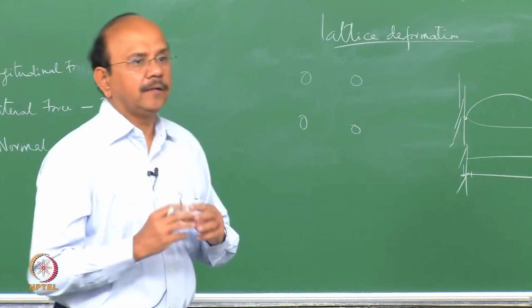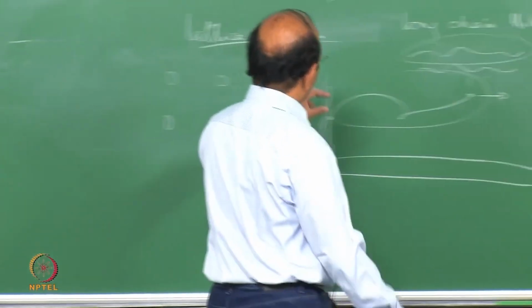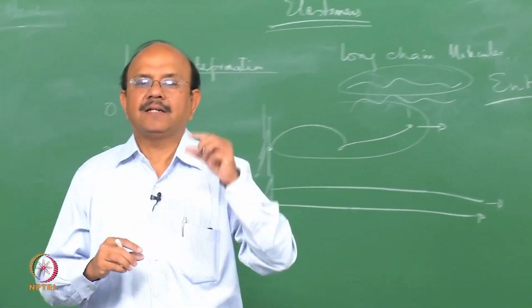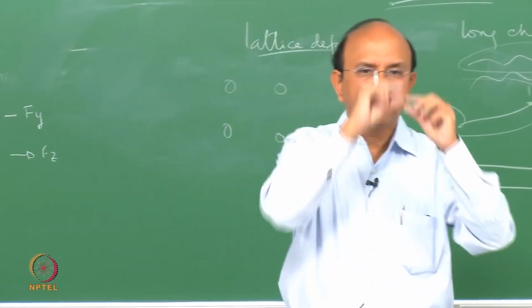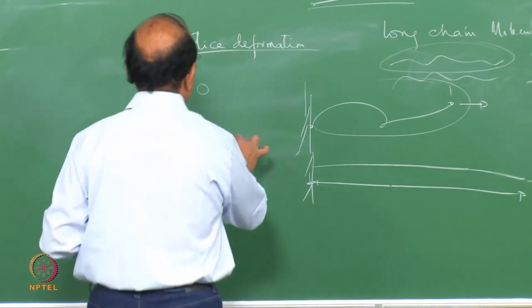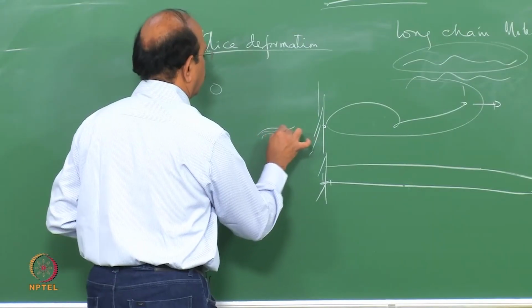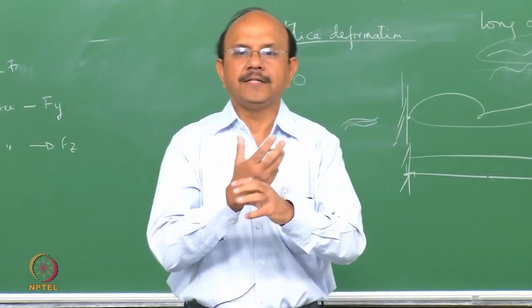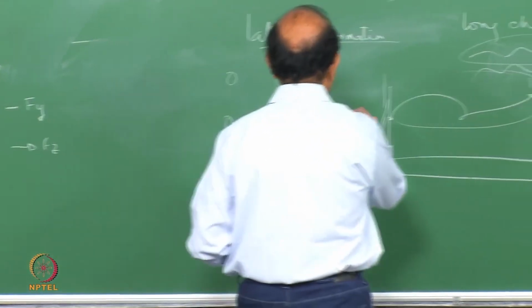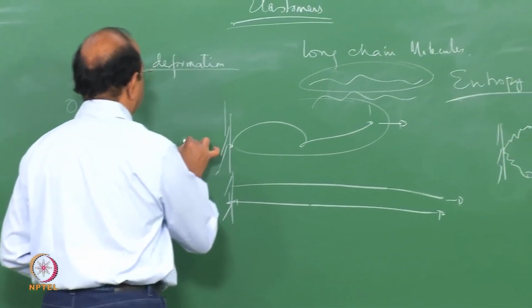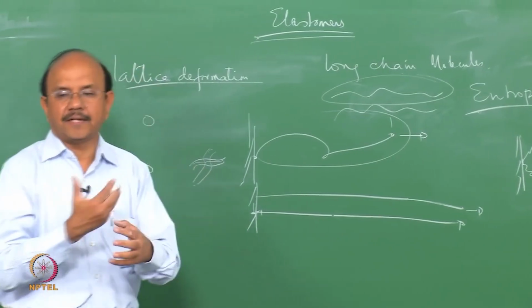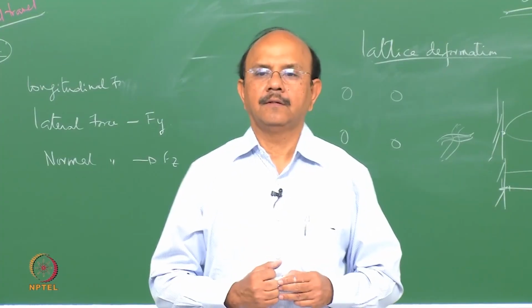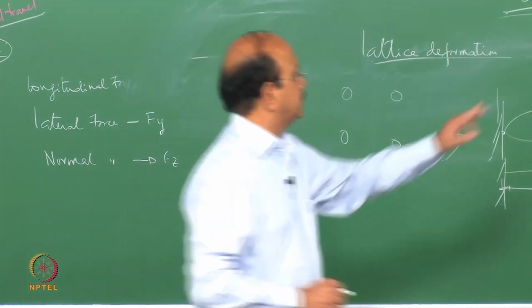You can, for a moment, imagine that these molecules are in a tube. This is called a tube model. The elastomer consists of a number of tubes into which these molecules are placed. And these tubes now start interacting; as the chain goes, there is a tube like that, and they start interacting with one another. Because of this interaction, I said there is a viscous part.